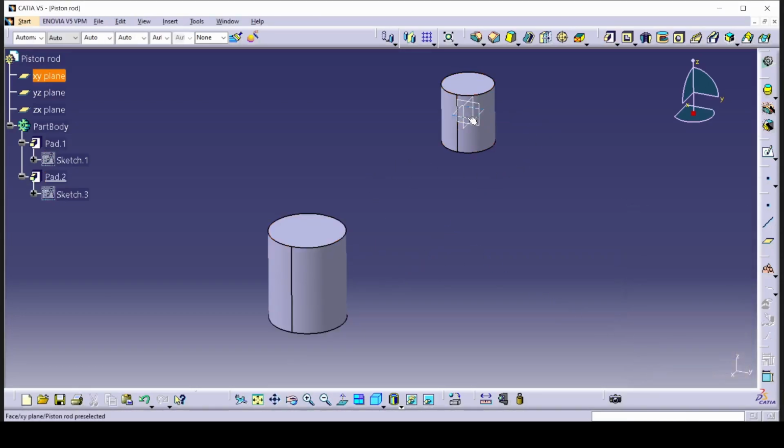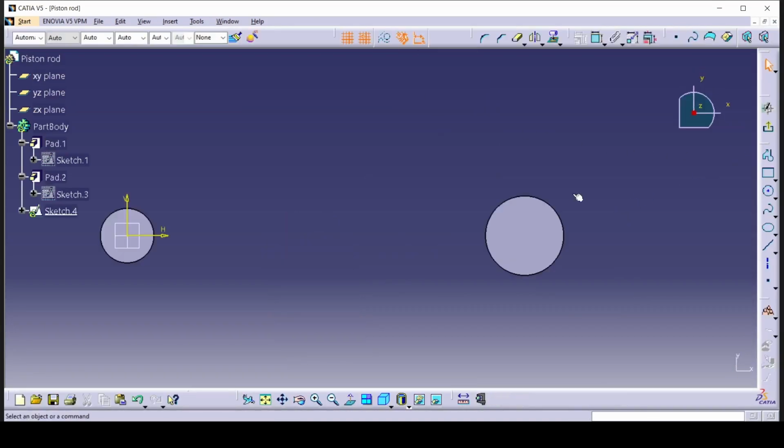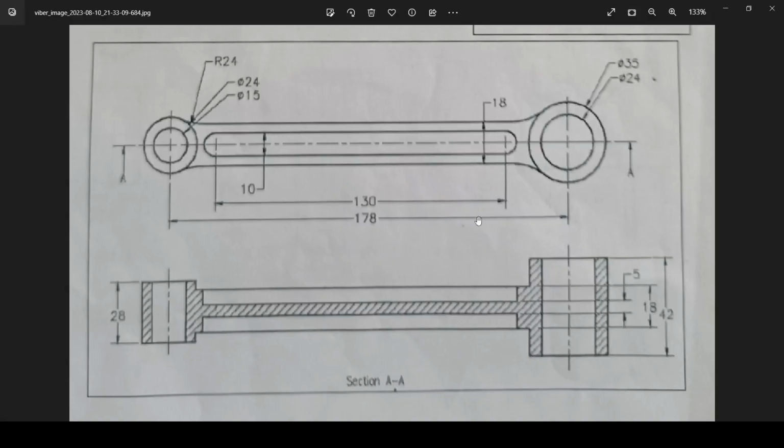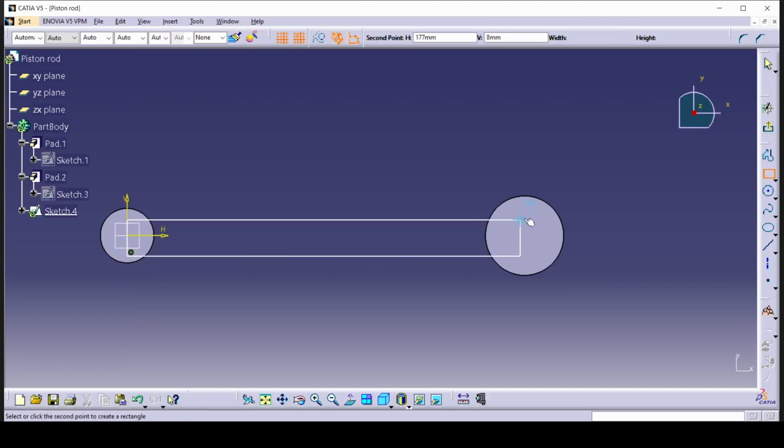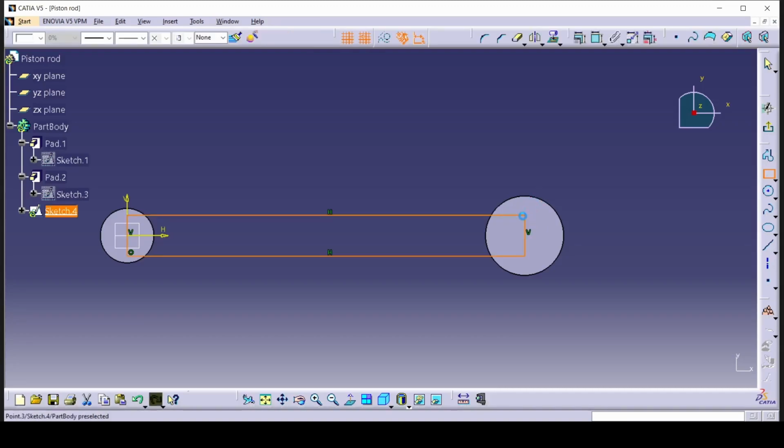We've got this part. Let's get back in here one more time, and now let's make a rectangle. A rectangle is going to go minus, let me actually check how big it is. So it is 18, so it should be minus 9 and 9 coordinates, because we made it here, not somewhere up here. So let's go minus 9 and up by 9. There we go. Now let's just save these parts.